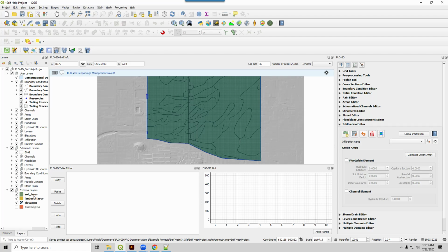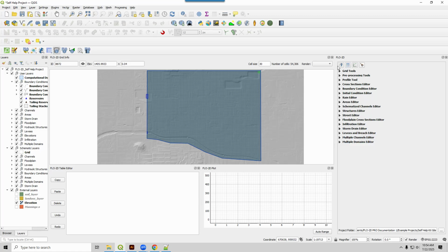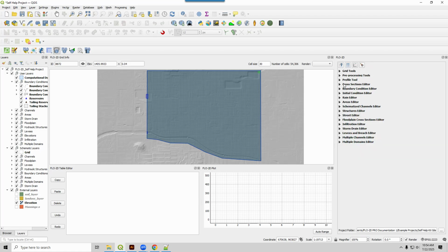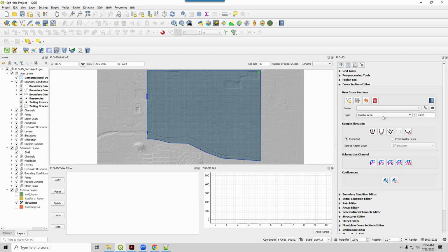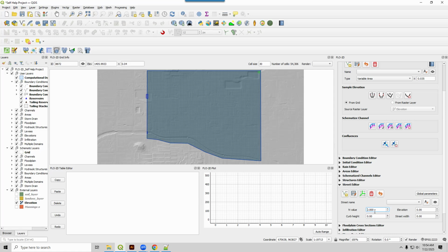And as you can see, they are no longer scratch layers, they are now permanent layers, but we don't need to see them anymore, so we can uncheck them and continue with the simulation. Continue with the processing. Now we're finished with Green-Ampt infiltration, so we can collapse that. Or if you have one of these opened, you can collapse it here. What I don't recommend is you use the roller wheel in here to move this up and down, because it will change values, okay?